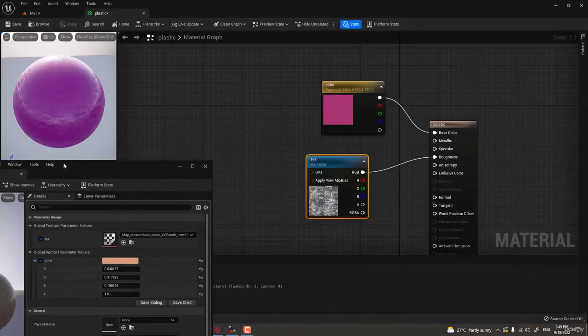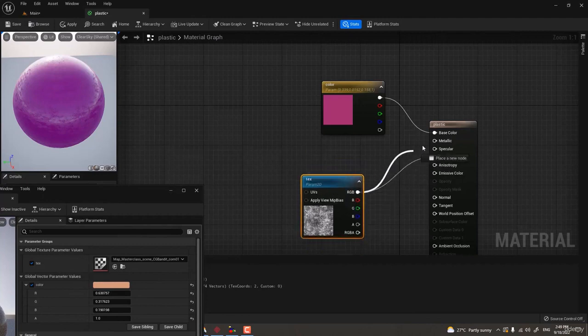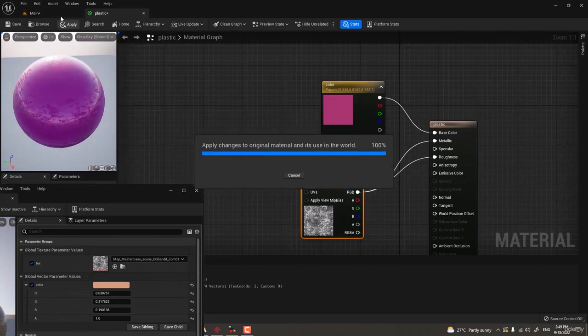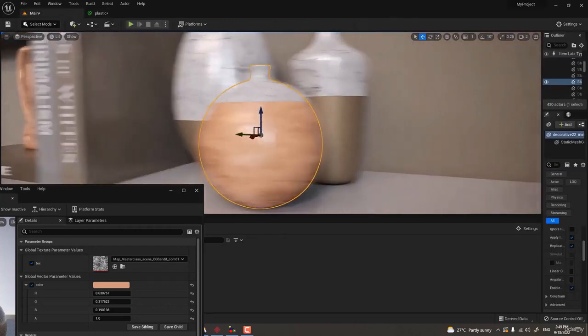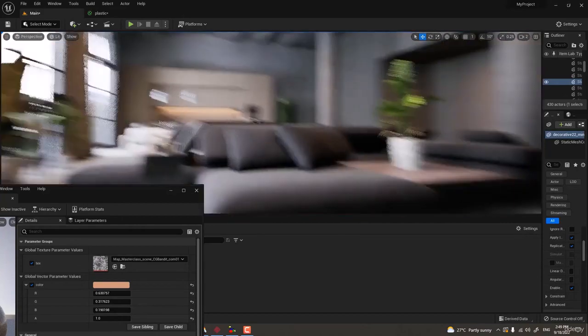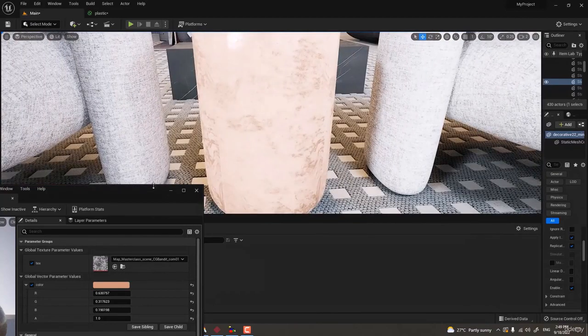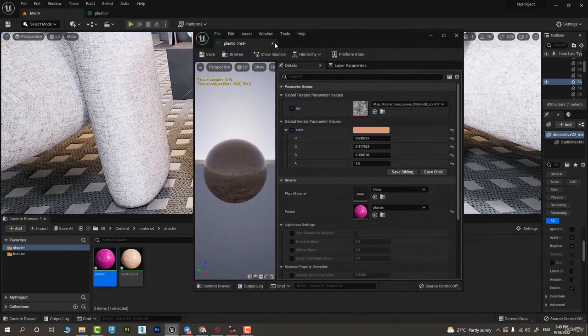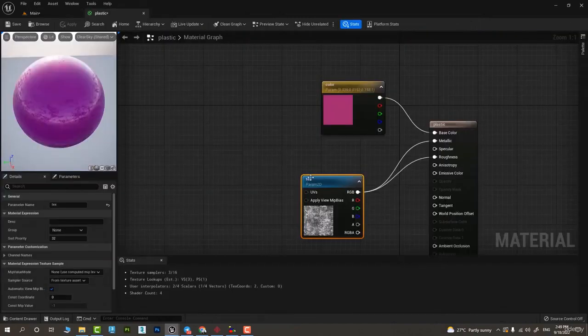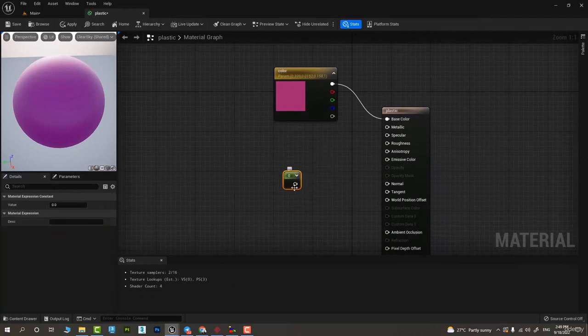We can do the same thing with metallic. I mean, use the texture, the same texture even for the metallic, and have kind of similar effects in terms of metal-like features. So let's go back to the main, hit apply, of course, go back to the main. All right, see, in some parts and patches it resembles a metal, and in some parts and patches it doesn't. Let's go back to that big object here, this object that I have here. You can see things more clearly in this. Usually we don't really use a texture for metallic like this, but more so for roughness. All right, let's move on and start talking about the specular.